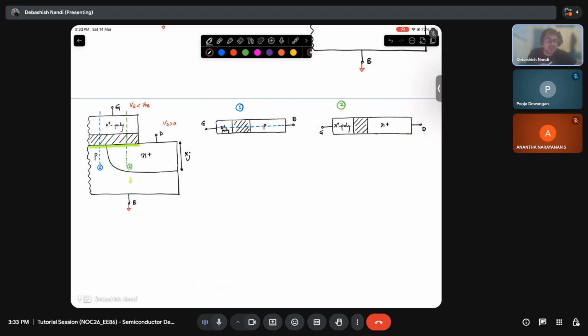is very small. For example, if xj is small, as in the case of FDSOI, more likely ultra thin body and BOX FDSOI, then, as you have correctly pointed out, we need to consider that additional body contact.